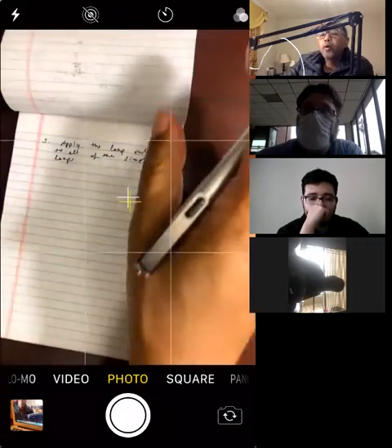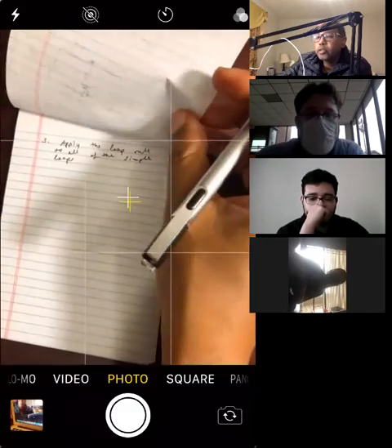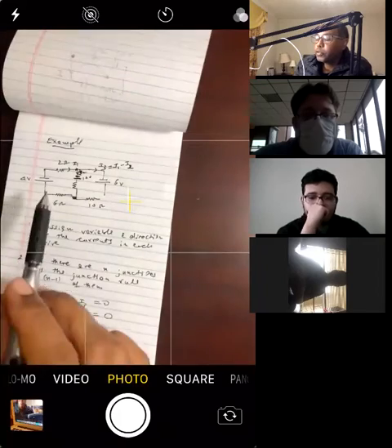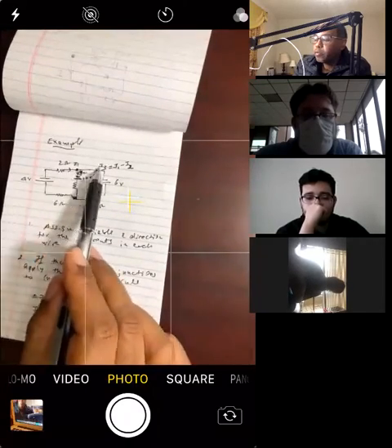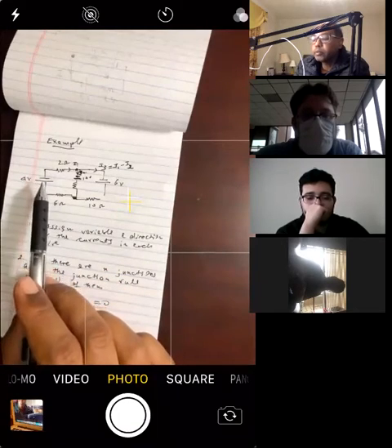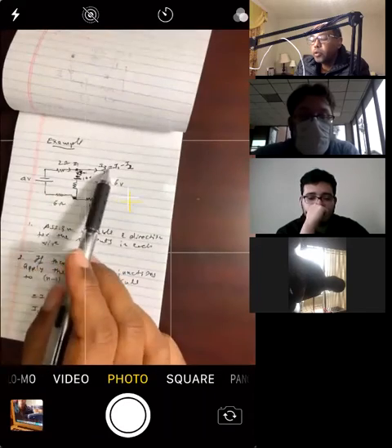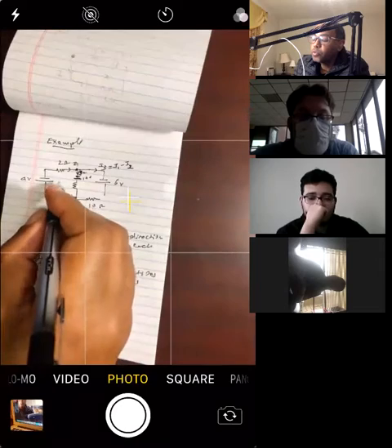Okay, so how many simple loops do I have? Can you tell me? In this circuit, remember, a simple loop is a non-intersecting loop. We have 3 loops in this circuit. We have one over here, one over here, and a third one over here. Which ones are simple? Just this one and this one. This one is not simple because it's an intersecting loop. All right, so I just have 2 simple loops.